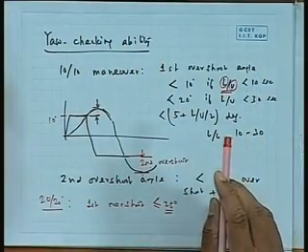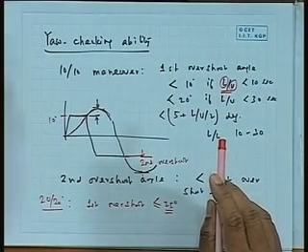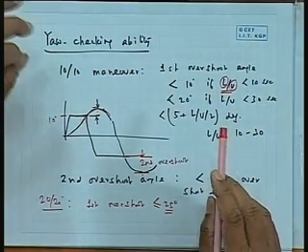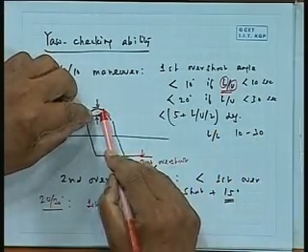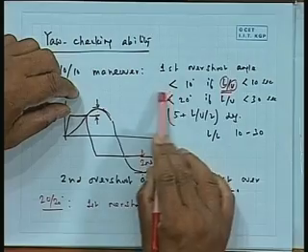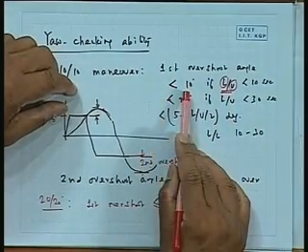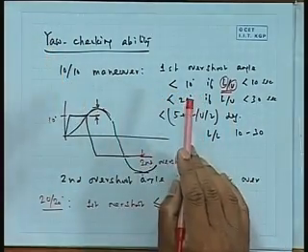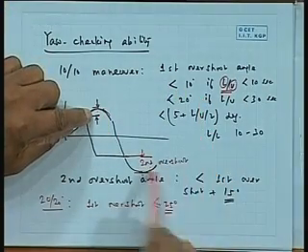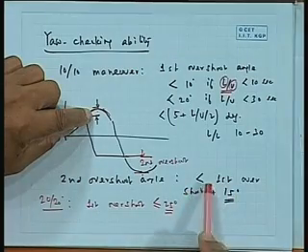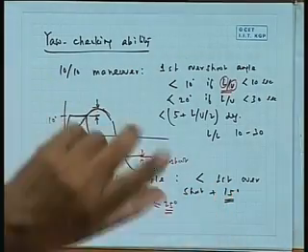The second overshoot should not exceed the first overshoot by some amount. Suppose the L by V of a ship is such that the first overshoot should not exceed 12 degrees. Then the second overshoot should not exceed 27 degrees. The second overshoot you will always find is larger, and in all these ships you will find that it goes like that, then like that, this one larger, then it stabilizes. Plus 15.